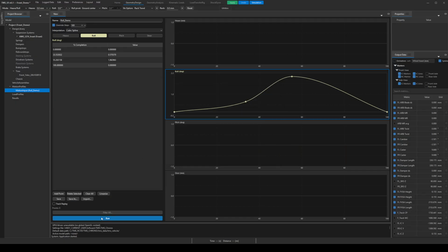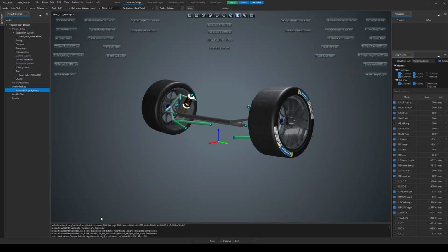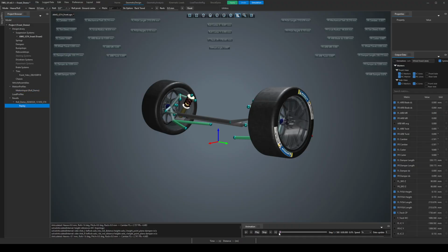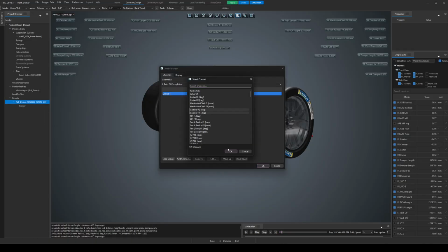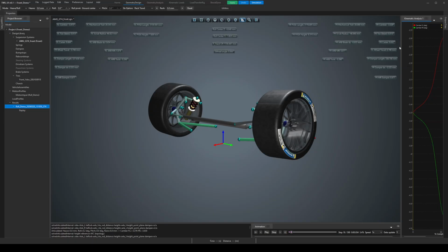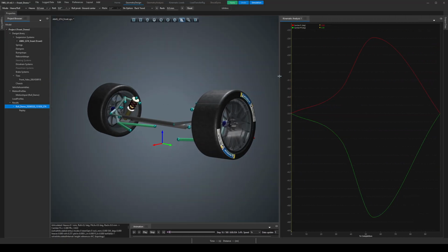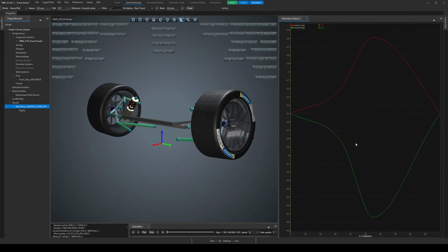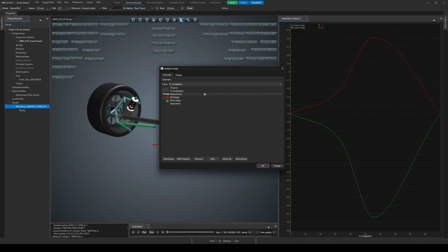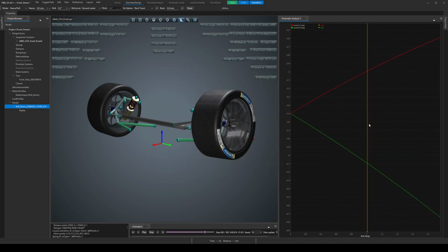Running the motion profile produces results in two views, live metric values on screen while scrubbing through the replay, or any chosen suspension metric plotted for closer analysis. The plot x-axis can be percentage of completion, wheel travel, or any other log channel, so this supports both standard time history plots and x, y style analysis.